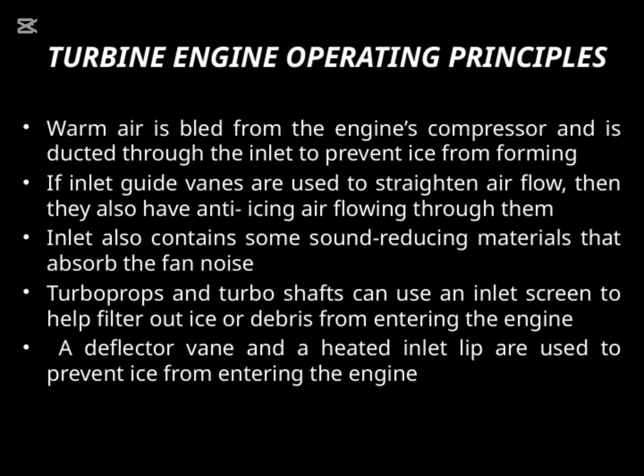You'll also see that the inlet contains sound-reducing materials. These materials are designed to absorb fan noise, making the engine quieter during operation, an important factor for passenger comfort and environmental regulations. For turboprops and turbo shafts, there's often an inlet screen. This screen acts as a filter to help block out ice or debris before they can enter the engine, protecting it from potential damage.